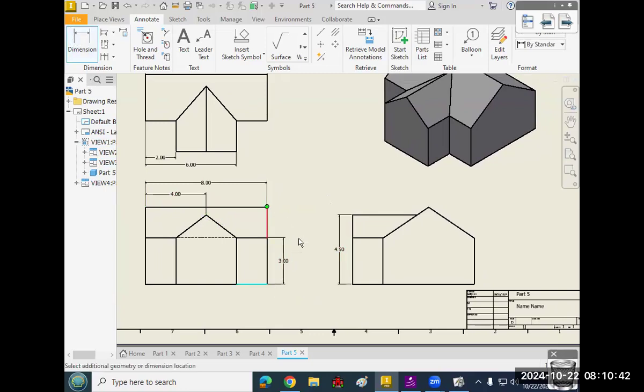And the only other height is total height, which here is fine. Here is also fine, but all things being the same, the long extension line is worse. Remember, the whole point is about avoiding confusion, and the more lines and the longer the lines, the less ideal. Okay, then depth, start front to back.